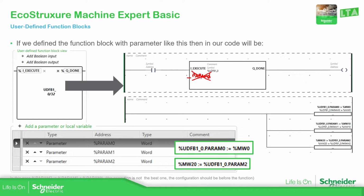So if it's one parameter for input, we just need to define it this way. We just need to define the name of the function block, the instance, dot, and the name of the parameter. In this case it is param0. And in this case, as a word type, I need to use a %MW value.